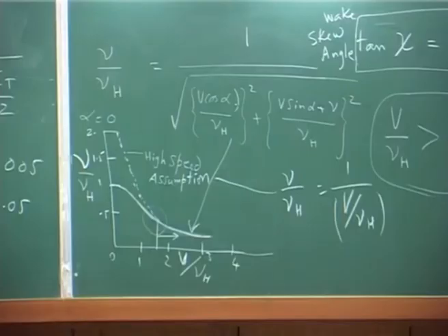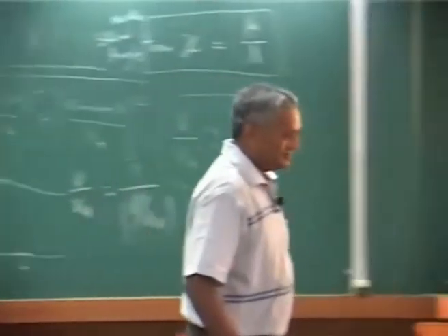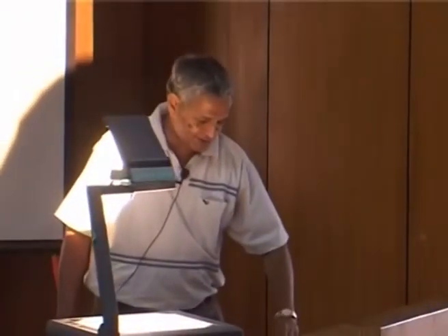All right. Now the question is, the rotor behaves like a circular disc. For a circular disc, we assume that the inflow is constant everywhere, but which is not true. There will be substantial variation in the inflow over the radial as well as azimuthal location. Then you have to have a theory. But this is only history, I will briefly give it. What we are going to do is, we will follow